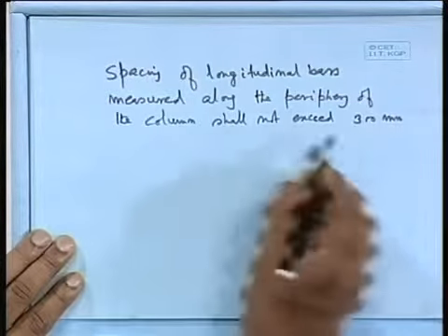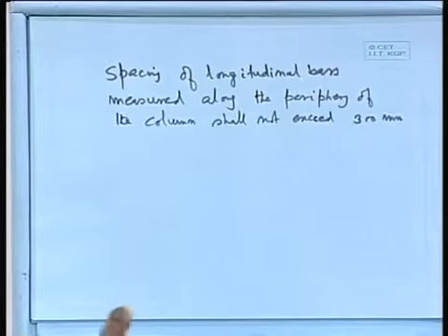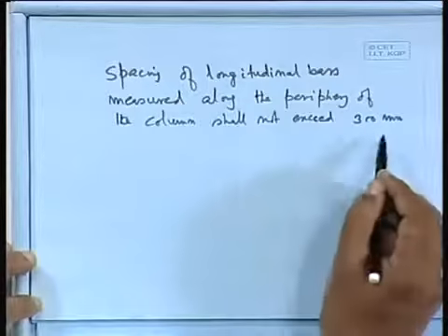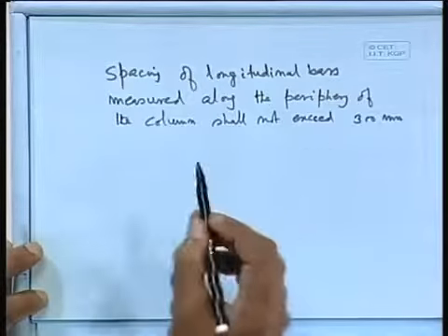That means the maximum gap between the longitudinal bars is 300 millimeter. If it is more, then we have to provide 2 numbers.